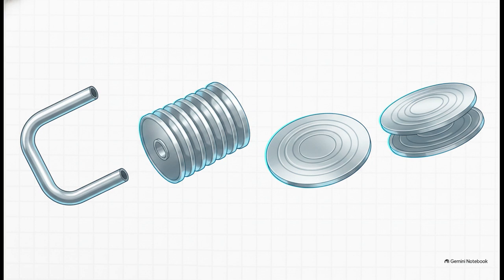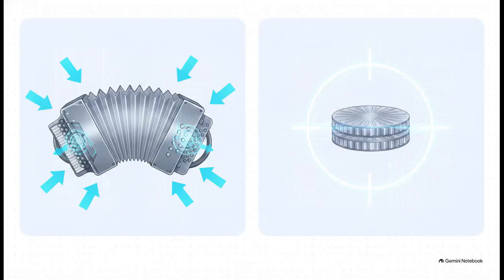Think of these as expanding, accordion-like metallic containers made of materials like phosphor bronze or stainless steel. And finally, we have diaphragms, which are thin, flexible circular membranes, and capsules, which are essentially just two diaphragms welded together. Let's see how this builds, right? Like, why would a facility choose one over the other? Well, bellows are fantastic because their expanding container design allows for a large degree of physical movement.